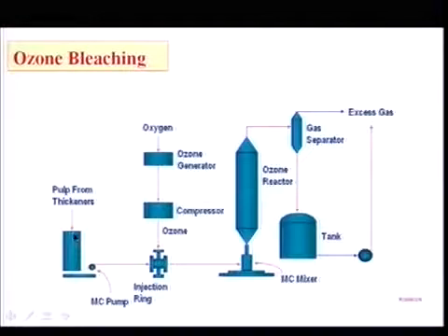The pulp comes from the standpipe with the MC pump, goes through the ring, where ozone is mixed, and then goes to a very small, short tower, because the retention time you need is only 5 minutes and it's at room temperature. You don't need steam here.